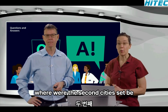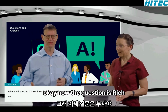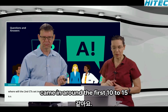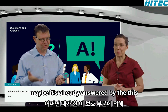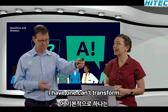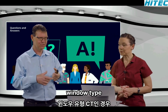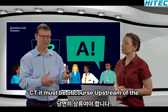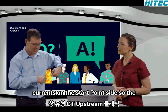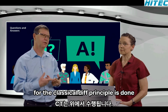Because NA wants to know, where will the second CT set be installed for the differential protection? Okay, now the question is which type of the differential protection? It was rather early during your presentation. So I think the question came in around the first 10 to 15 minutes. Maybe it's already answered by the diff protection part, which I did. Basically, I have one current transformer upstream and one on the start point side of the motor. If it's a classical differential protection, if it's the window type CT, it must be, of course, upstream of the motor, because I need to get the current that comes in and compare it with the current that comes out. So I cannot compare both currents on the start point side. So the window type CT upstream, the second CT for the classical diff principle is then on the start point, as we saw.